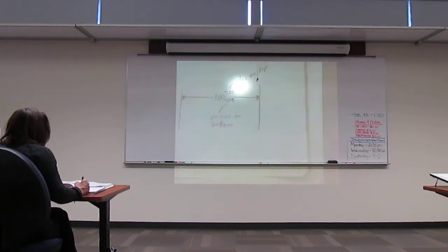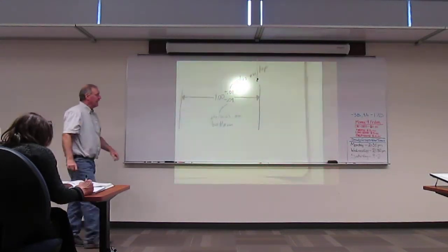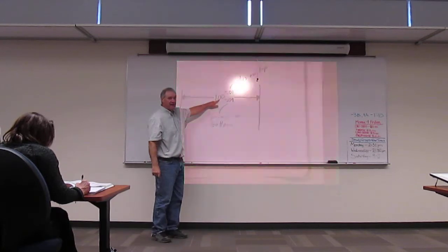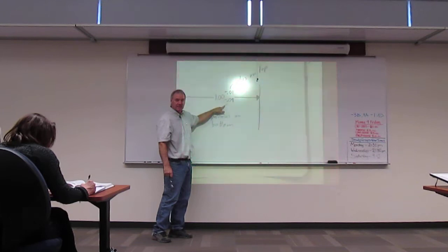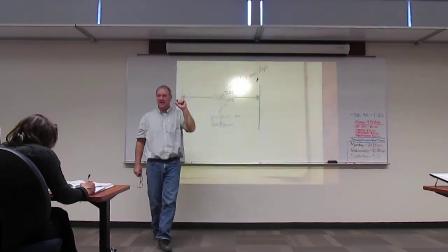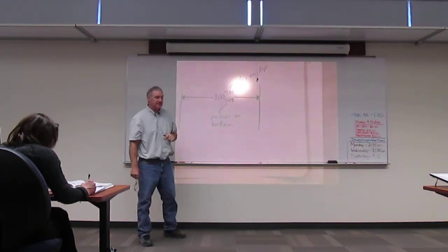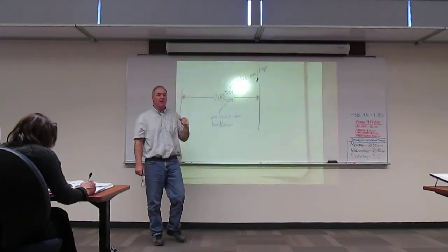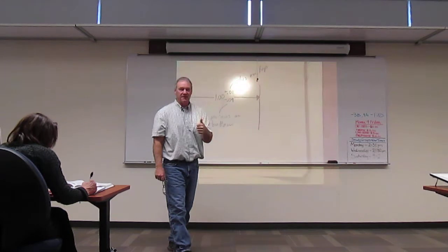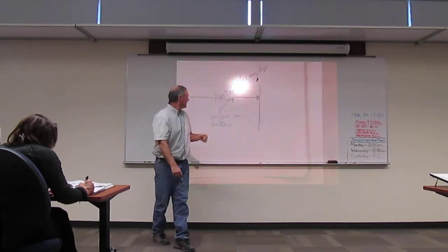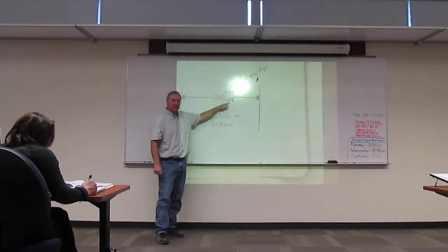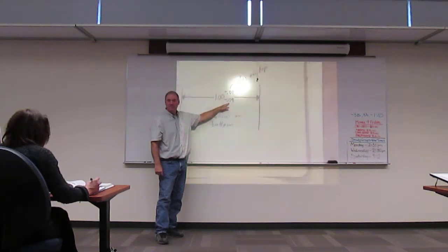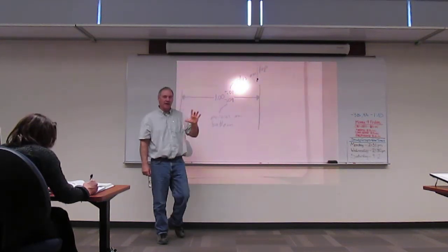Okay, where I would put my dimension, this is my basic size, and then I put the deviation from that with half of the size text, so this would be 16th text, and I put plus 0.01, so I'm allowing them 1/100th of deviation in the positive direction, but then I'm going to allow them 4/100ths in the negative direction. So we can mix that up.